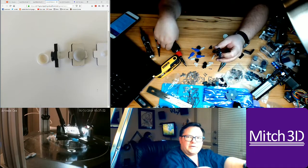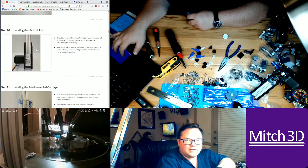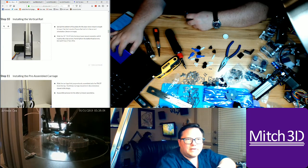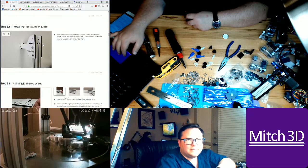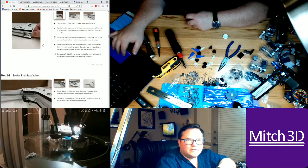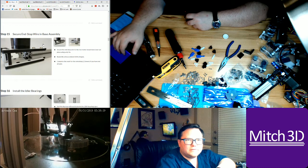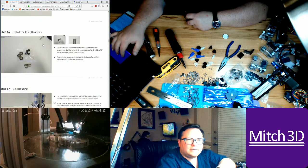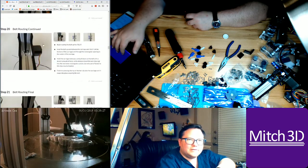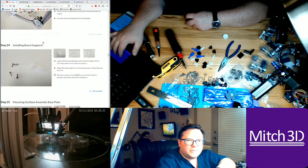I think it's pretty progress. I think there's not a lot left, honestly. Well, there's a lot left, but it's not like a Rostock build. The Rostock Max build takes forever. So right now we're going to be putting the rails on and the carriages and the top mounts. It's going to go together really quick here. The end-stop wires are going to go through. Have to solder end-stop wires, and that shouldn't be an issue. Secure them with a zip tie, idler bearings, belts, belt routing, then your top and base assemblies.